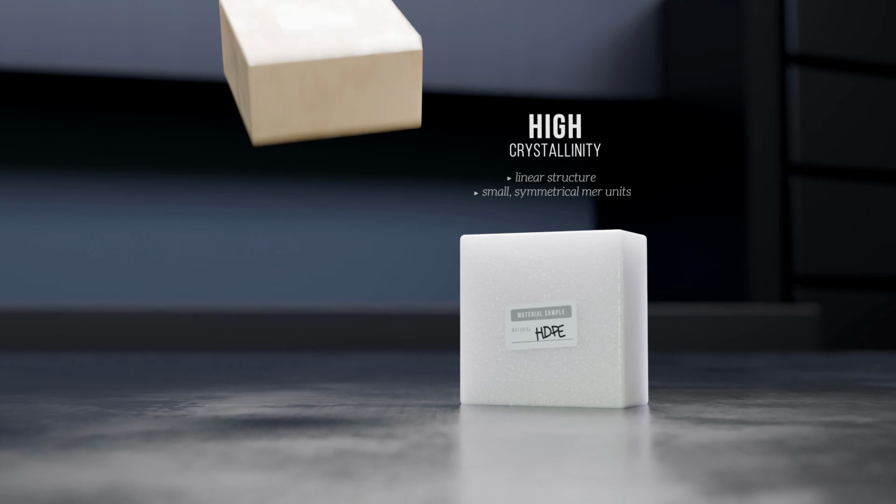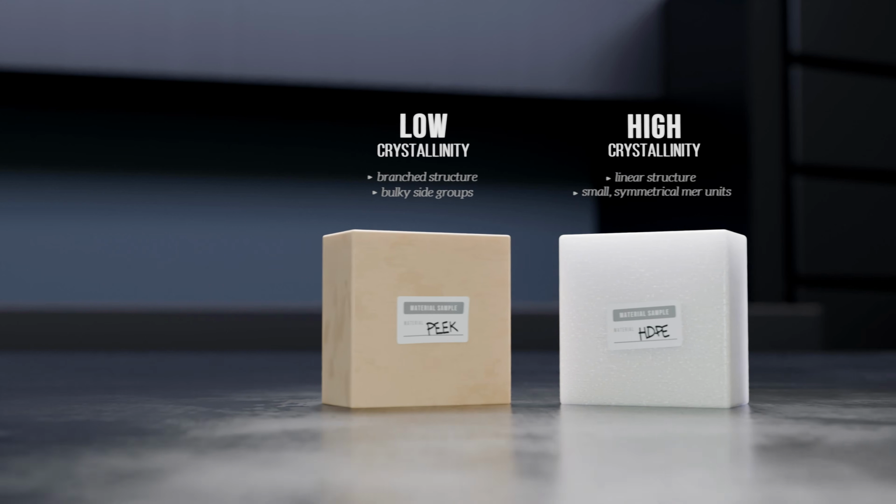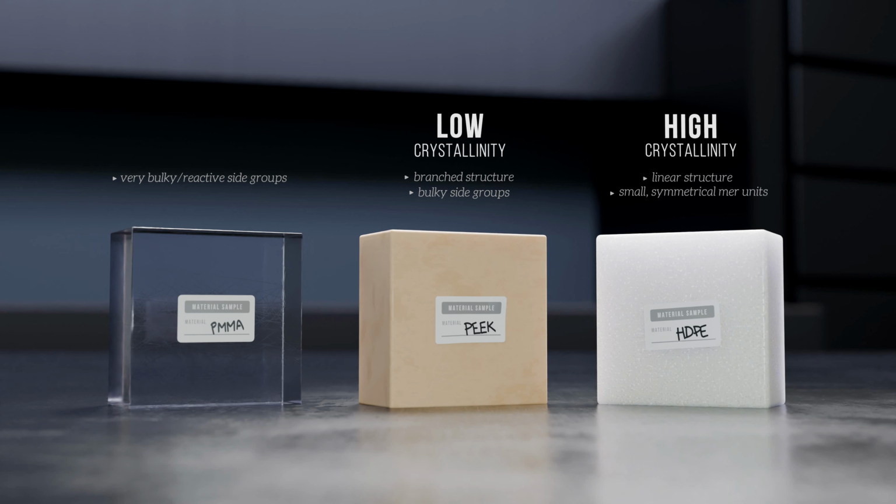Branched polymers, or those with other features that prevent close packing, like bulky side groups or irregular mers, tend to be much less crystalline. And some polymers that have very bulky or reactive side groups are completely amorphous, because the side groups completely prevent polymer chains from arranging themselves into an ordered structure. This is also true of cross-linked polymers, because cross-linking prevents polymer chains from forming ordered structures. Polymers with a high degree of crystallinity tend to be stiffer, stronger, and have a higher melting point than more amorphous polymers, because close packing creates stronger intermolecular forces.